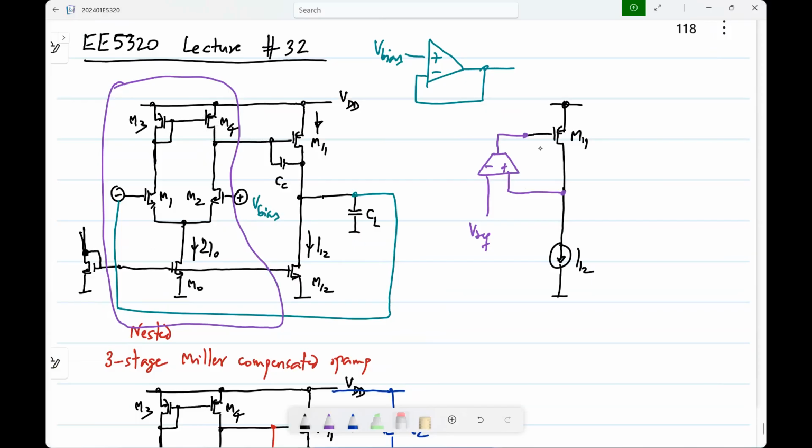Wherever you have two current sources connected together, ideal current sources, unequal values, it doesn't work at all, right? I mean, it just violates the basic circuit laws. If you have transistors, of course, the transistors will not be ideal current sources to begin with. And in any case, once it moves to the triode region, it's not a current source at all. It's a low impedance, low resistance device. So that is what is going to happen. It is going to go out of the desired range of operation. But it's only when you place the op amp in negative feedback that all the transistors remain in the saturation region.